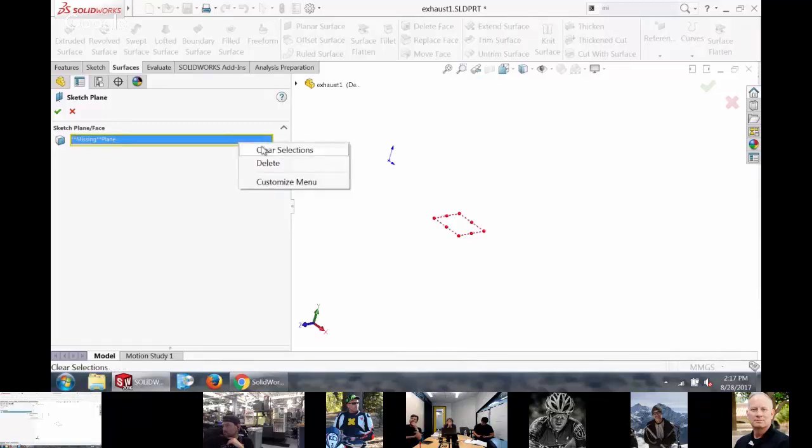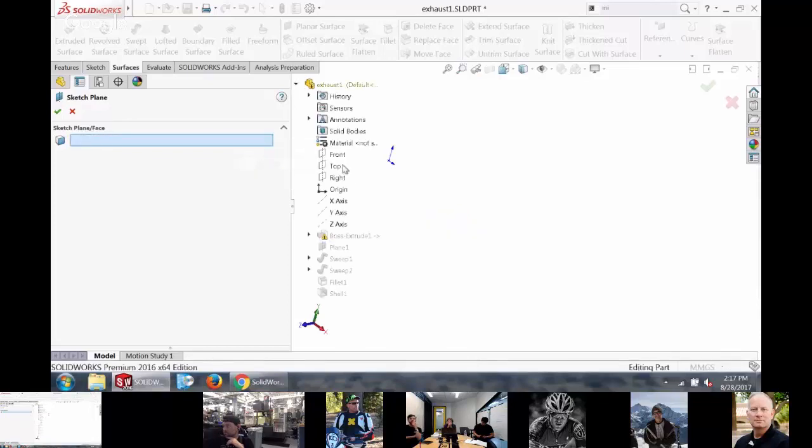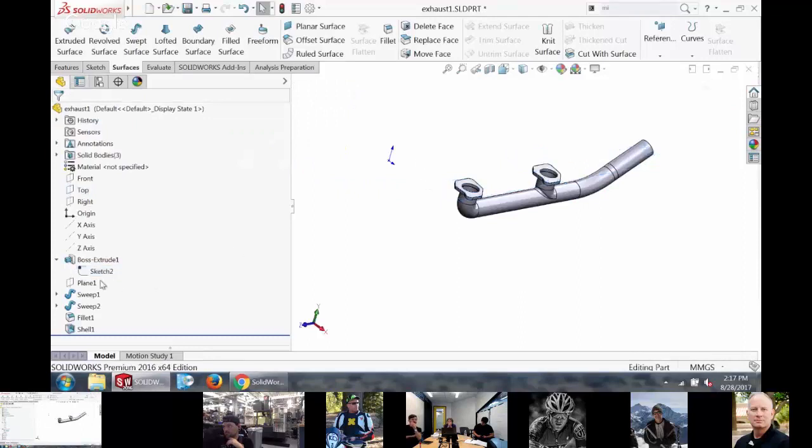So all I need to do is delete this thing that it's got and use some other sketch. And now you see all my external references are gone. So to get rid of an external relation, there's a couple things you can do. You either need to go into the sketch and get rid of dimensions or relations like on edge or offset that are from geometry in the assembly, but you also have to go into where that sketch is being drawn on.